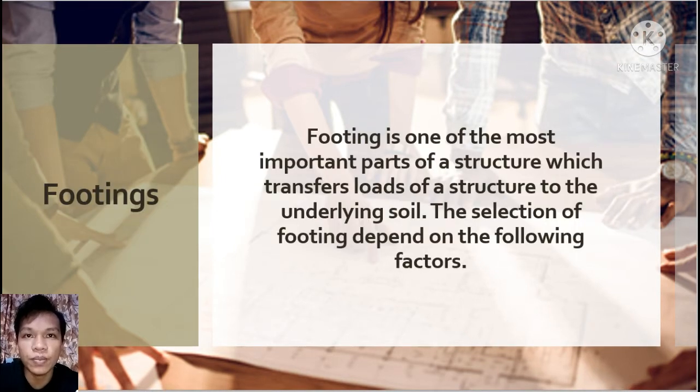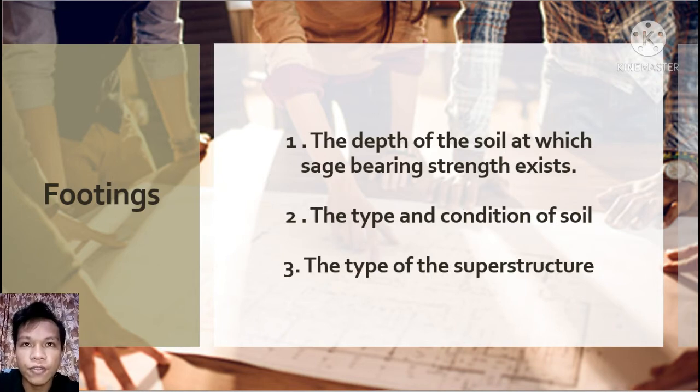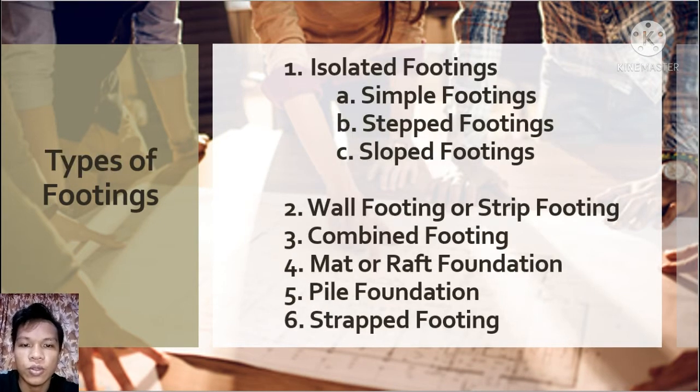Footing is one of the most important parts of a structure, which transfers the load of the structure to the underlying soil. The selection of footing depends on the following factors. First, the depth of soil at which safe bearing strength exists. Second, the type and condition of soil. And the third is the type of structure.